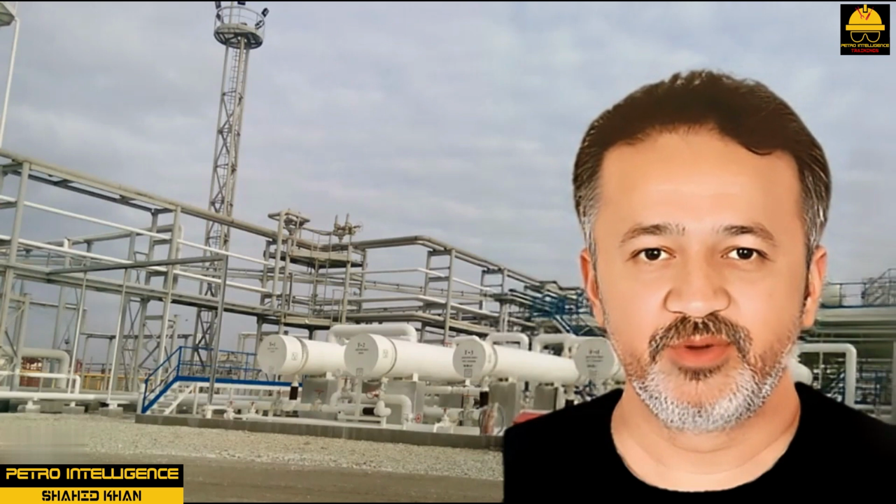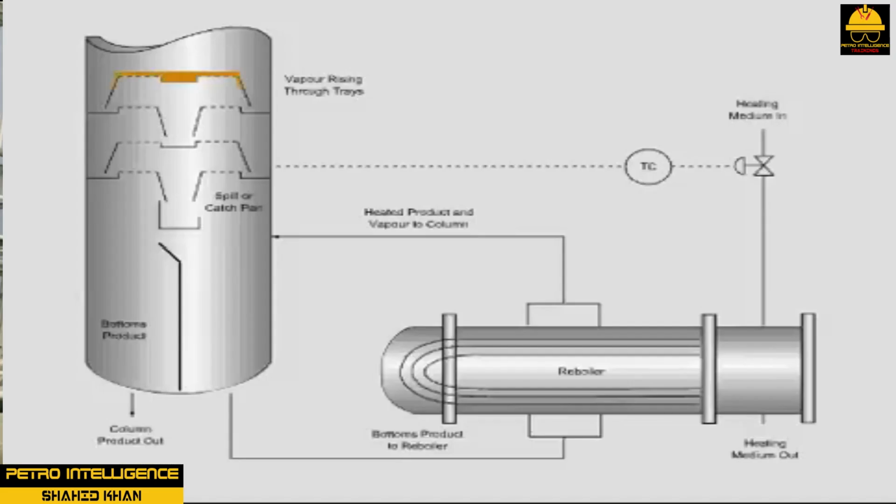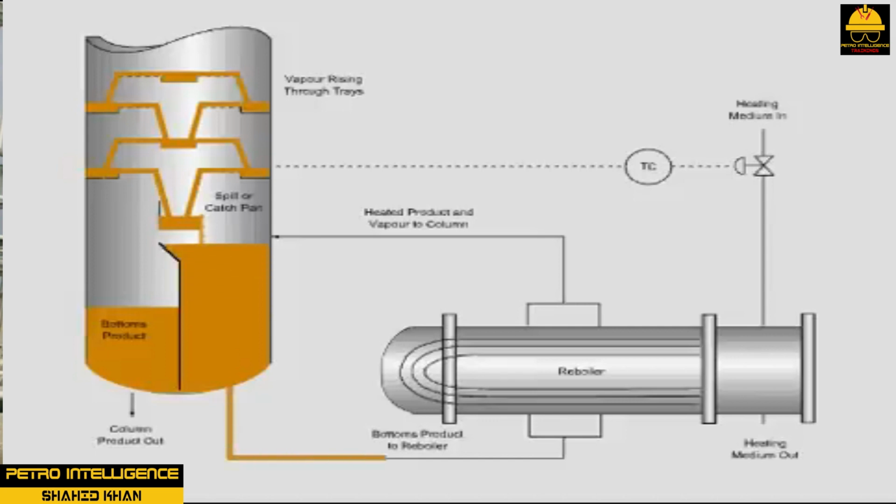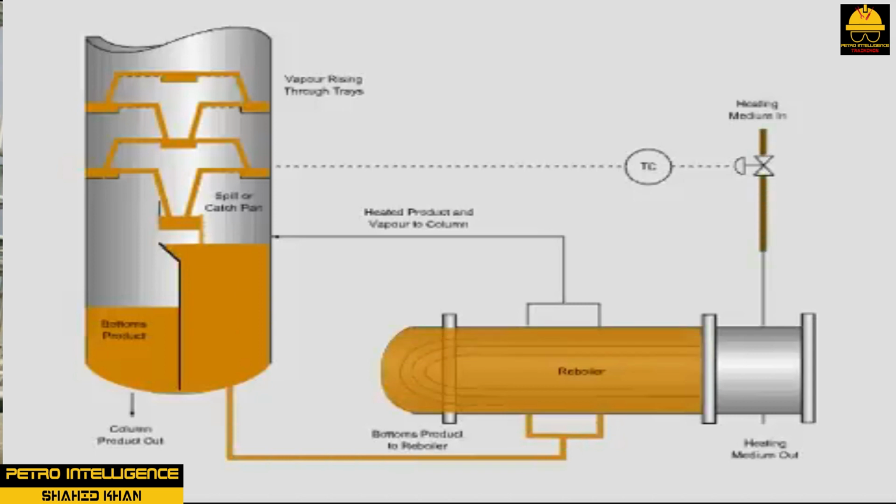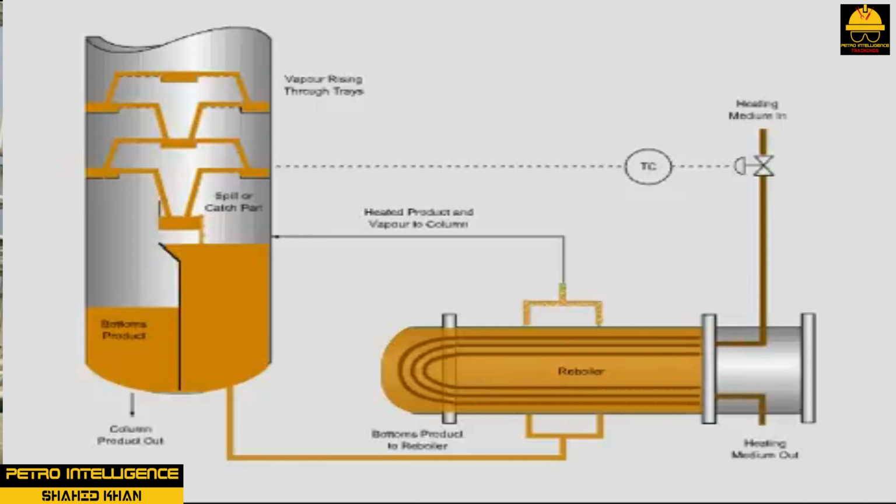Vertical and horizontal thermosiphon reboilers. A thermosiphon reboiler is a fixed-head, single-pass heat exchanger connected to the side of a distillation column. Thermosiphon heat exchangers can be mounted vertically or horizontally. The critical design factor is providing sufficient liquid head in the column to support vapor or liquid flow back to the column. Natural circulation occurs because of the differences in density between the hotter liquid in the reboiler and the liquid in the distillation tower.